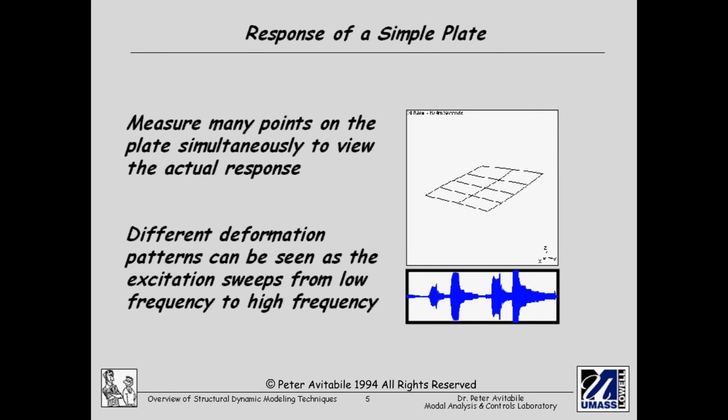And then at the next two large amplitudes of response, we're going to see that the structure is going to have a frequency of vibration that's going to be the second bending mode and the second torsional mode. So at each one of these frequencies, the structure takes on a very unique displacement pattern depending on the frequency at which it is vibrated.